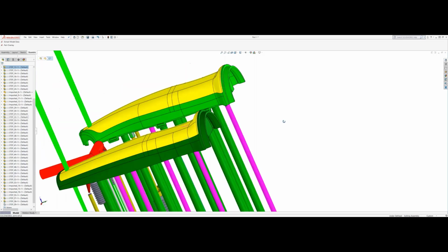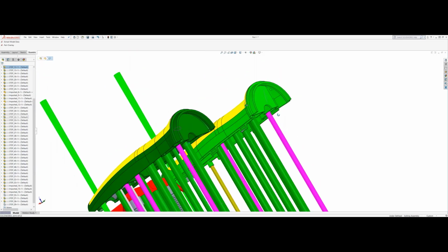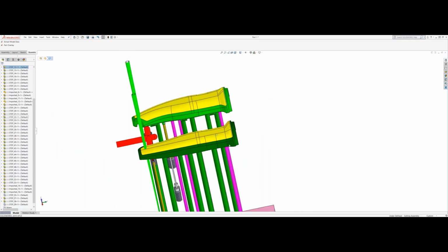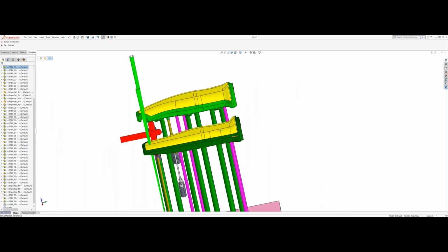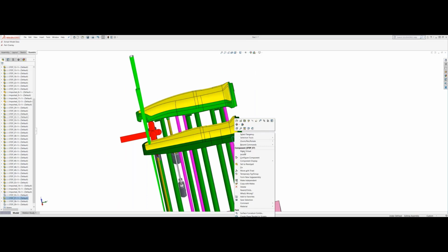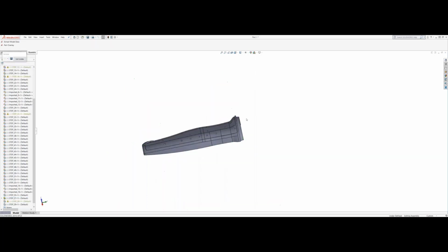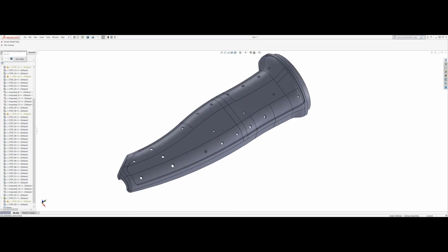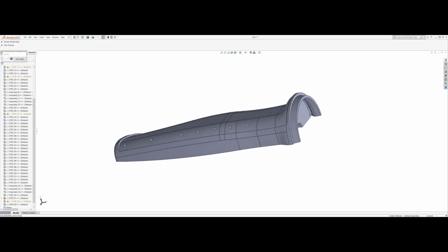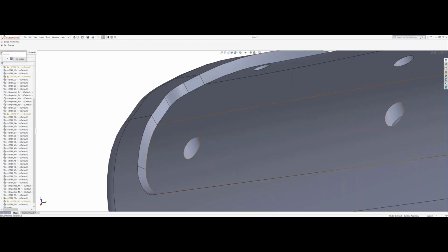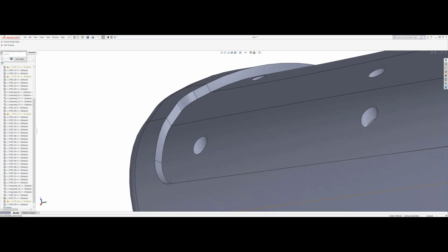for the end use doctor, nurse, whoever was using it. The adhesion of the rubber overmold material to that substrate, it has to be nice and tight, fully packed out, full. The mechanical bonds that we're showing right there, the holes, all that has to be good. We don't want any of that peeling away afterwards, so it's definitely a challenge. Get that to fill perfect every time without any ratty edges, and it actually holds and adheres to the substrate.